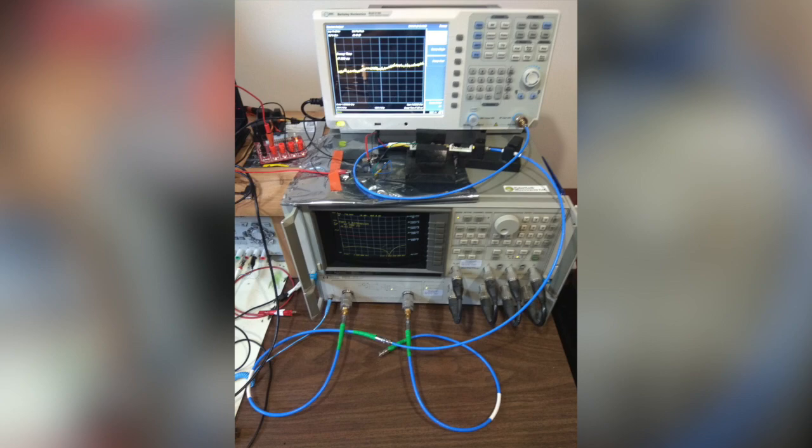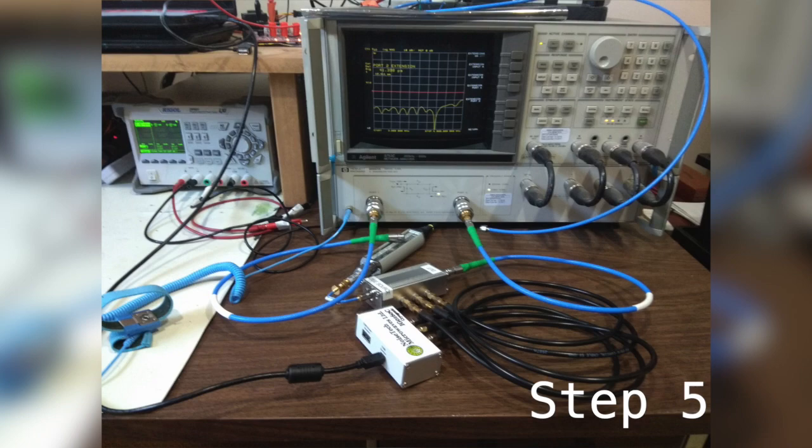So the lower the power, the better. The only thing you want to consider when lowering the power is that you'll increase the uncertainty on your VNA power measurements. So you might want to reduce your IF bandwidth to maybe 1 kilohertz. Depending on the speed of your VNA, that will slow it down quite a bit because it's averaging more noise out of your measurements. The next step involves measuring the reflection coefficients of the impedance generator.